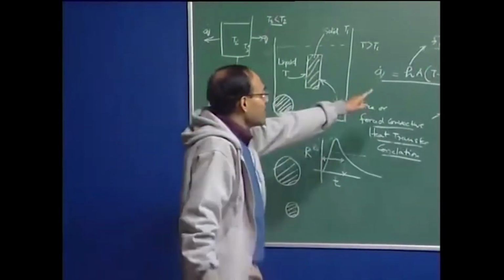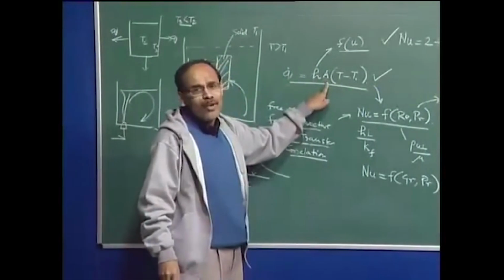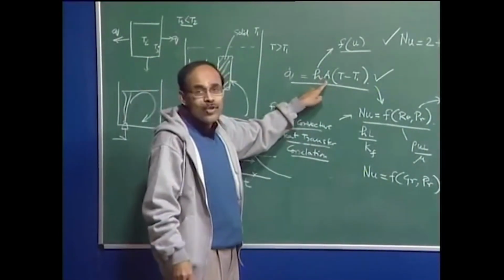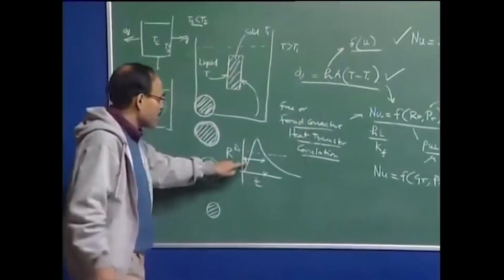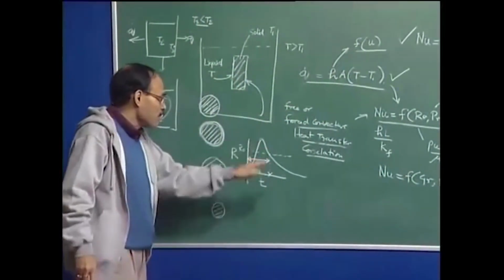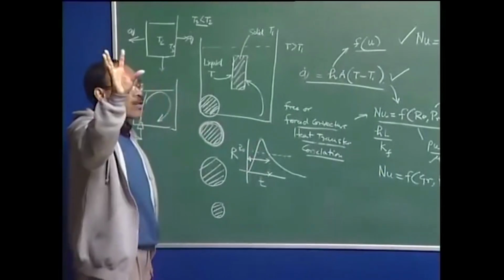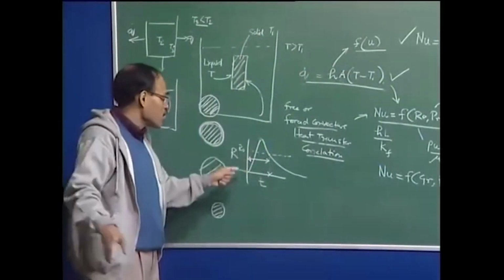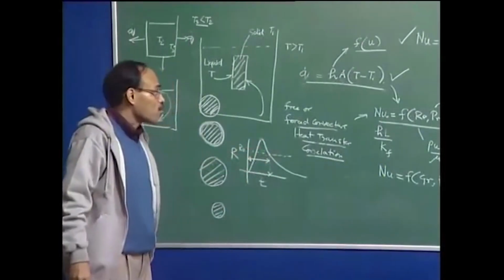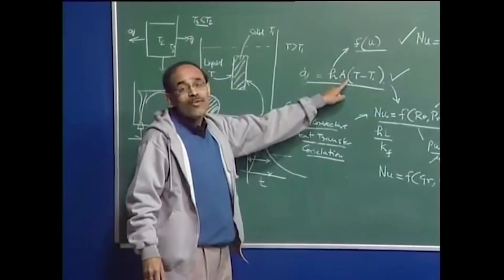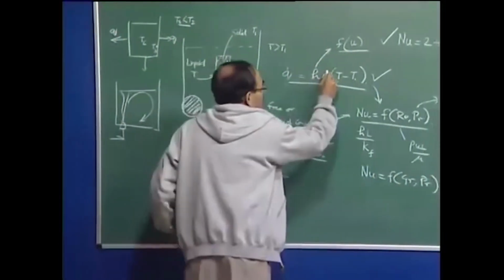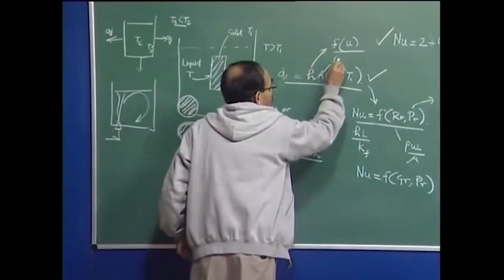So, this area that I have used in the rate expression will not remain constant during the melting scenario. This is going to continuously change as I have indicated. If you take 4 pi r square, which represents the surface area of a sphere, it is understood that 4 pi r square is going to continuously change during the process. So, taking an initial area is going to be highly misleading in this particular case. So, this A is going to be a function of